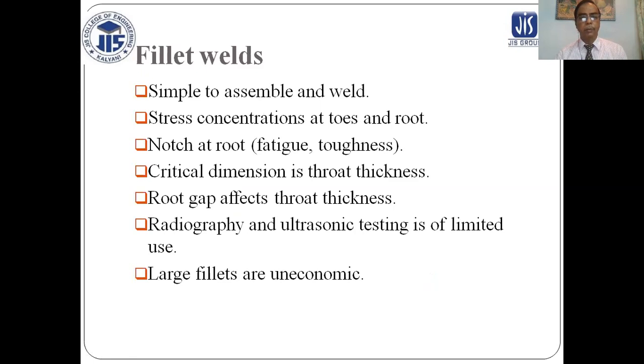Fillet weld: simple to assemble and weld. Considerations at the toe and root: notch at the root, fatigue and toughness. The critical dimension is throat thickness. Root gap affects throat thickness. Radiography and ultrasonic testing are of limited use. Large fillets are uneconomical.